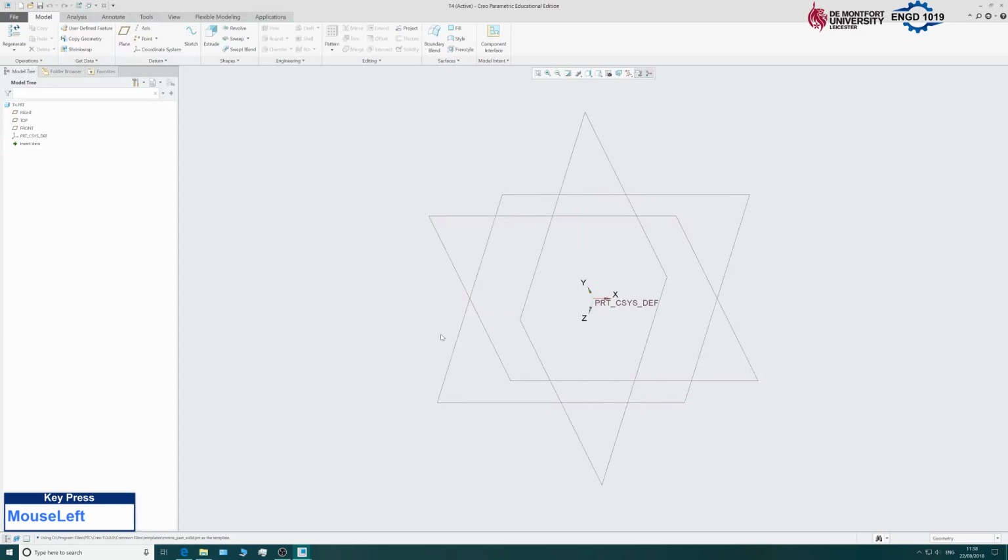Okay, so now we're in here. I'm going to start off with this component, and if we have a look at the engineering drawing, you'll see that all the dimensions are basically from one of the baseline end of this component. So I'm going to start off at that end, and you will see that we start off with a threaded section, and this is an M20 thread. So what that means is that the external diameter for this component section will be 20 millimeters. Okay, so I'm just going to start off by drawing that.